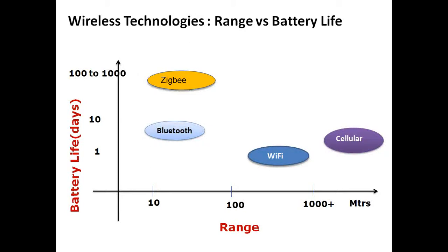Bluetooth has a little less range than the Zigbee, but it has a higher bandwidth in terms of what you can transfer over it. The less than 32 kilobytes for Zigbee and less than 250 kilobytes for Bluetooth is essentially how much memory it takes to implement the stack or the technology of the Zigbee in a particular microcontroller. And the reason that is important is the lower the memory is, the cheaper it is to implement this particular stack. So obviously Wi-Fi takes about a megabyte to implement, Bluetooth takes 250 kilobytes, and Zigbee the least.